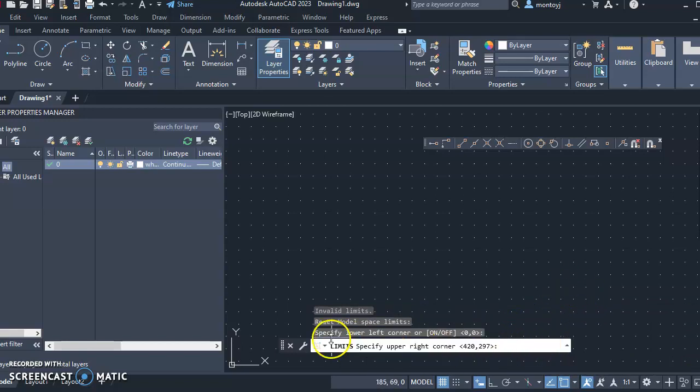I think this is the first time the train has run since the hurricane. So, okay, I didn't do this right. Let's do this again. Limits. The first number you enter is 0,0. Enter. Okay, the next number. For the first time ever, I'm going to be doing a negative number. So let's get the full keyboard. Negative 200, comma, which is important to have. If you remember, a couple of weeks ago we talked about that comma helps you get your coordinates.